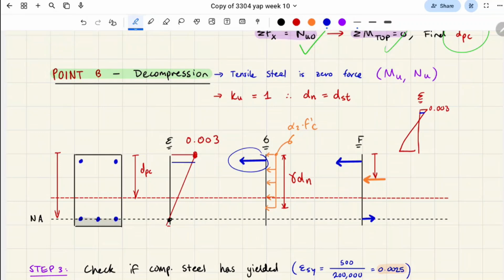So here, the bars are being compressed, and the tensile bars aren't being pulled at all because they're on the neutral axis. Whereas in our normal bending case, the tensile bars are being pulled a lot, and the compressive bars only a little bit because they're not very far from the neutral axis. So in our normal case, we generally assume the compressive bars have not yielded.